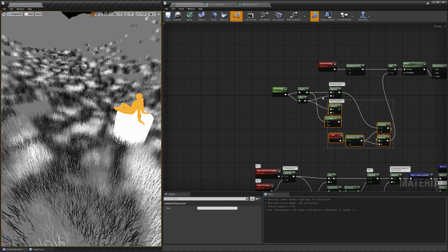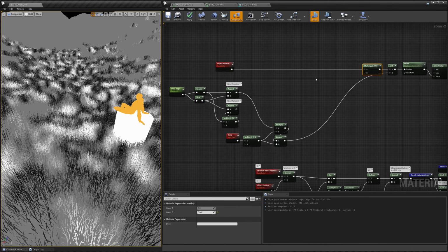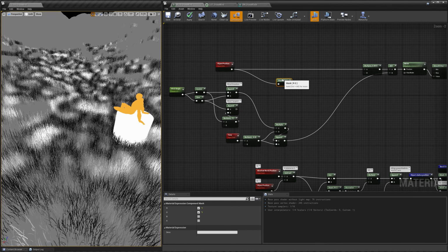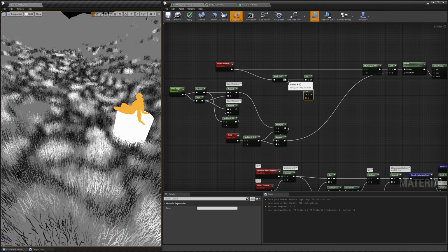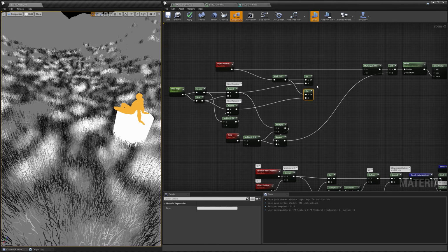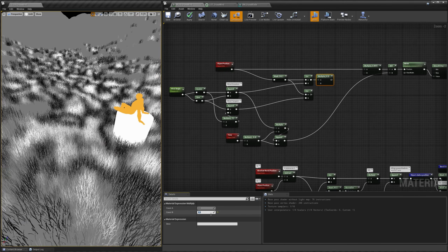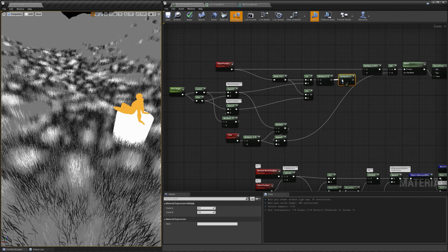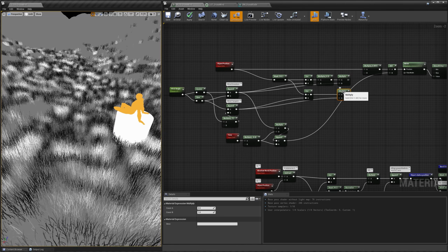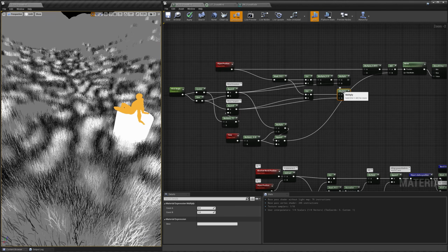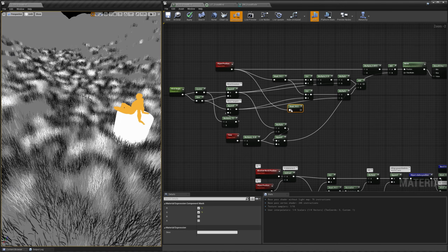And let's do the dot product of both these vectors with the xy object position vector. And now we can just scale one of these components as we want to stretch the noise. After that, we can recombine everything back to the usual workspace coordinates by multiplying these values by their respective vector, adding the result together and appending back the third coordinate.